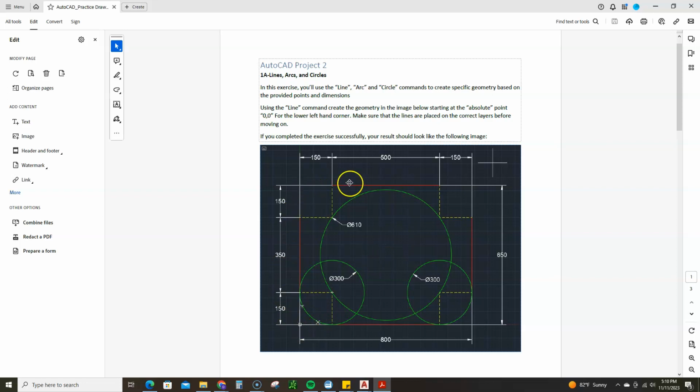We do want you to go ahead and create this basic rectangular shape where you're going to create a series of rectangles and circles based on line types, okay, using layers. So what we're going to do, we can see right now we have an object layer that's white. We have a red solid line, a yellow dotted line, and a green solid line. So right now we know we have 4 layers that we need to create, not including the dimension layer.